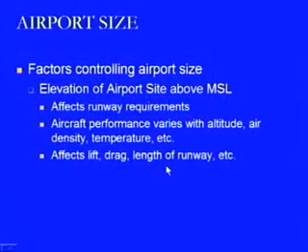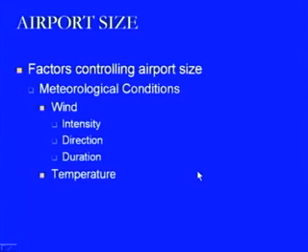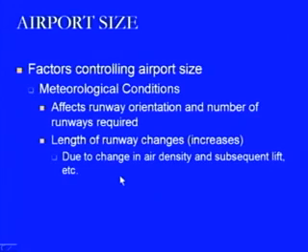And these are some of the things related to the airport site selection, like the number of runways required, and aircraft performance, which varies with altitude, density of air and temperature, and has its effect on lift, drag, length of runway, etc. Then in the meteorological conditions, wind is to be considered in terms of intensity, direction and duration, and then there is the effect of temperature. They affect the runway orientation and the number of runways required, and the length of the runway increases because of the change in air density and the subsequent lift, etc.